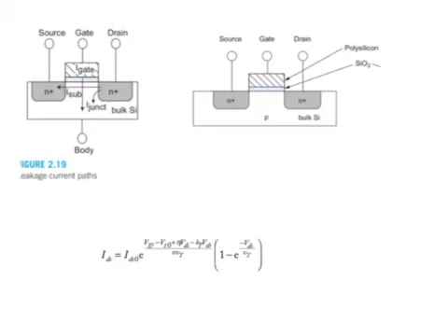And in short channel devices, because of the reduced voltage swings, there is a requirement to reduce the threshold voltage to accommodate smaller voltage swings, due to drops in VG and VDS from 5 volts to about 1.1 volts. The lower threshold voltage, VTH, that is frequently designed for these devices causes a significantly higher quantity of current that leaks. Now, there are three major mechanisms through which current leaks in a MOSFET.